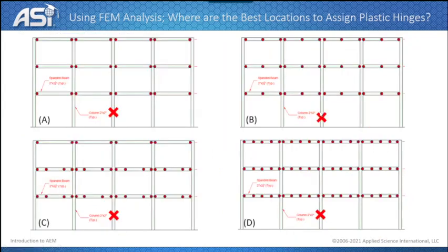So engineers, when they are doing progressive collapse analysis or seismic analysis using simplified nonlinear analysis programs, have to assign what's called the plastic hinge location, where they define the behavior of this hinge location. They define what we call the moment curvature curve, the behavior of the connection during the analysis.